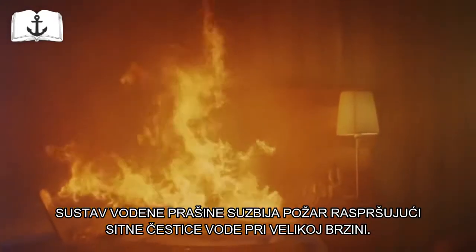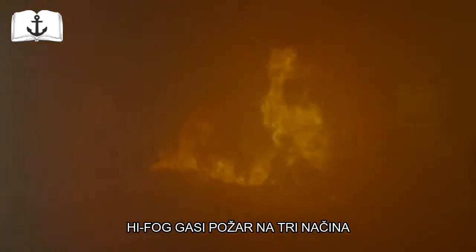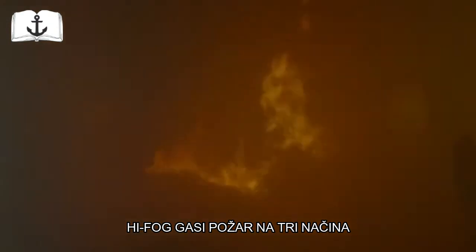High fog suppresses fire by discharging a fine water mist at high velocity. High fog fights fire 3 ways: by cooling the space, by blocking radiant heat, and reducing the oxygen that reaches the seat of the fire.